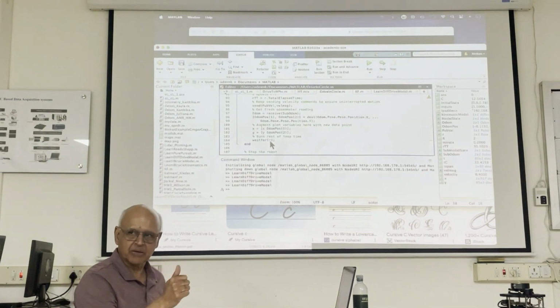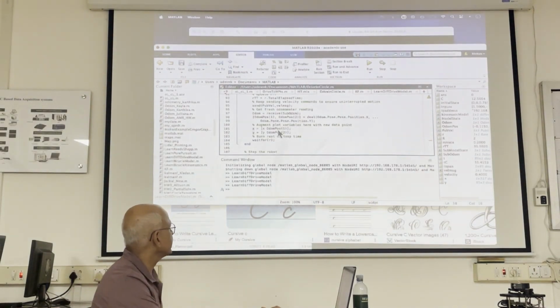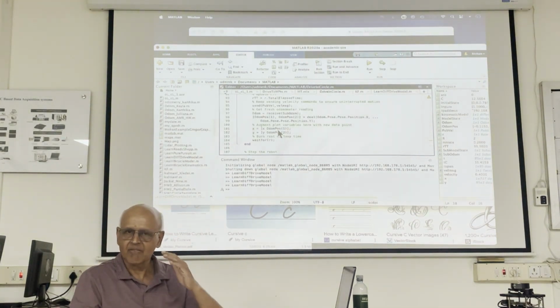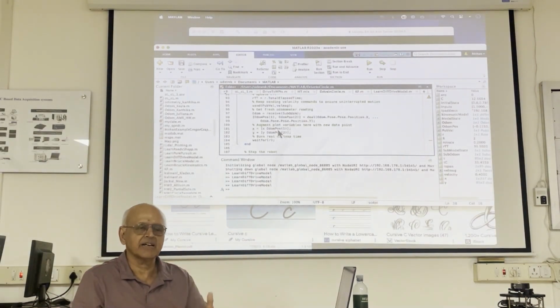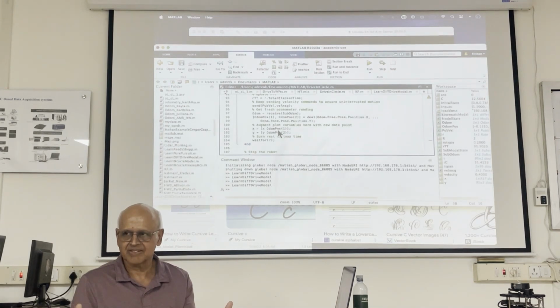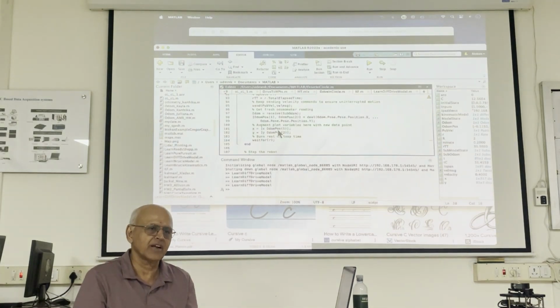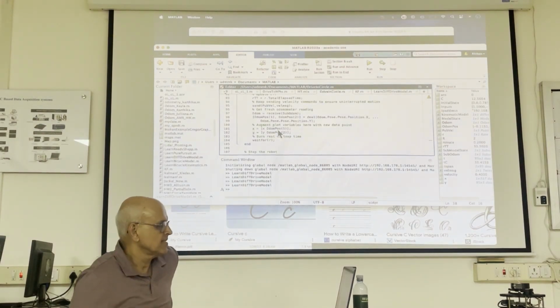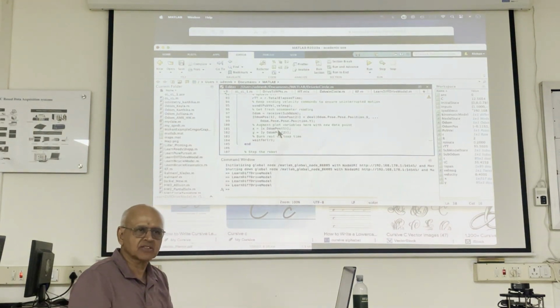That means once every 100 milliseconds, this loop is executed. You know what rate they use for self-driving cars? It's 10 times that, 100 Hertz, because you're moving much faster. So you cannot afford to be slow. So the loop time is 10 milliseconds. Now, why not 2 milliseconds? Now remember, you have finite resources. So you don't just go crazy because you don't know what the right number is. There is a right number which you can find for every application, and you run it only as fast as that. So people seem to have settled on this 10 milliseconds for self-driving cars.